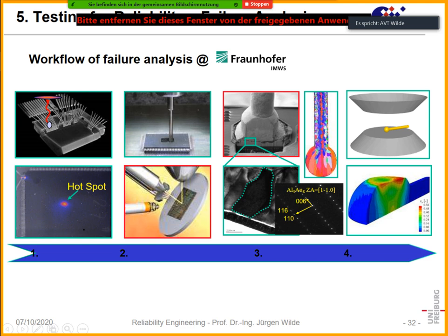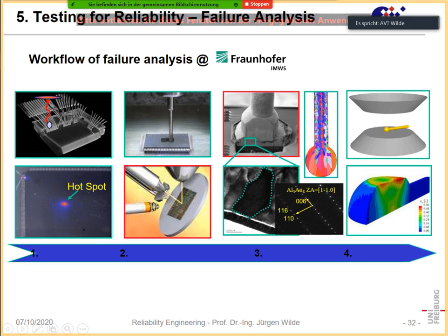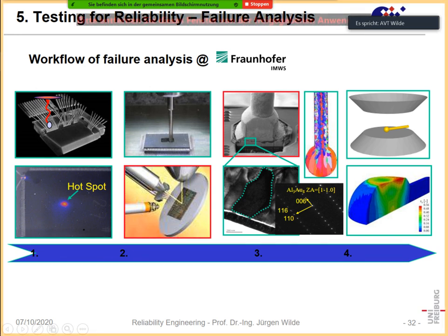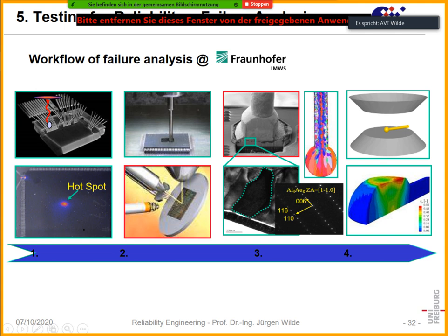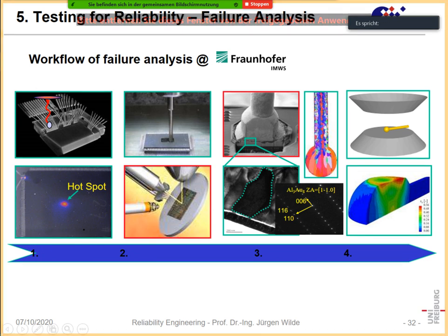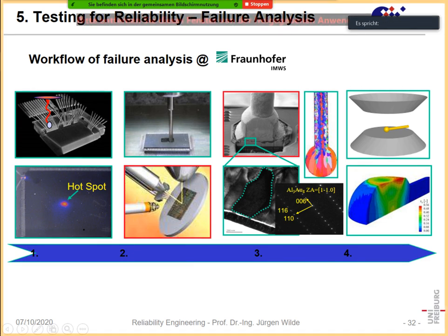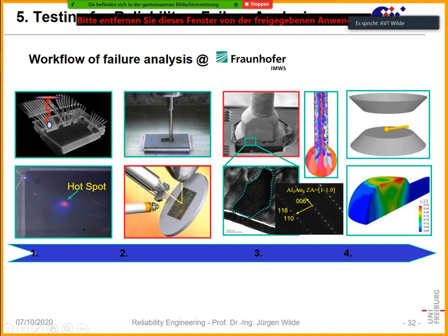A focused ion beam is a small probe of a high energy ion beam which has a diameter of, let's say, 10 nanometers. And with that beam, we can cut through very small features here, like this bonding wire. So we can see here already the internal structure. That is a wire bond which has been cut through the length. And when we address such a wire bond here, which was on the chip, we can see here there are cracks. We can see the crystal structure under the bond, and that crystal structure can be a result of some brittle phase. For instance, here it was analyzed that this phase is something like Al3Au8. That's an intermetallic phase, which is brittle, and here this will create a crack.